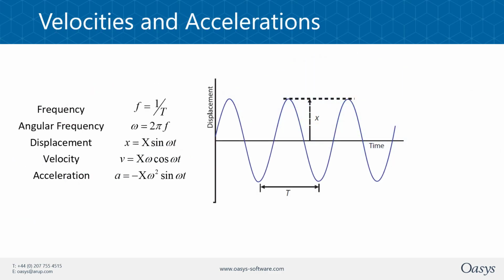And when you have calculated the frequencies from the vibration modes, you then need to do a subsequent analysis to calculate the velocities, the displacements, the accelerations, and so on. The accelerations might then be in terms of the peak acceleration, or root mean squared, or root mean cubed, and you might express them in meters per second squared, or percent g. And similarly velocities might be in terms of meters per second, or MIPS, and so on. Look at your design guides for the recommendations of what it wants from the analysis.